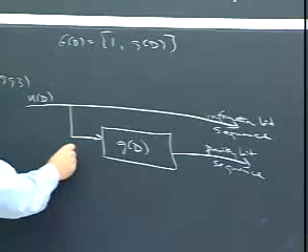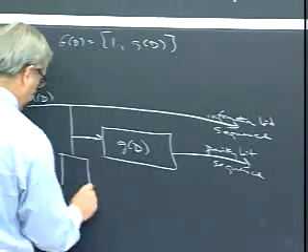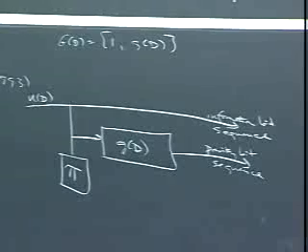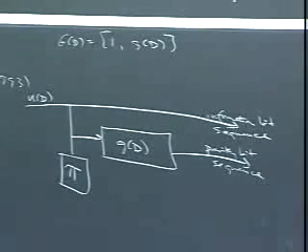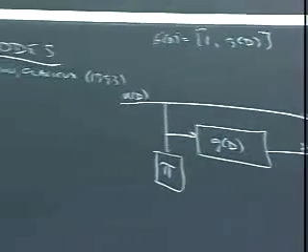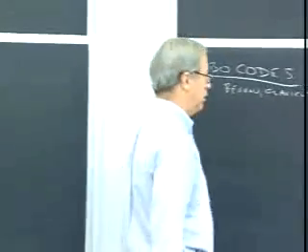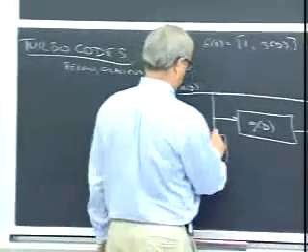Now, let me take the same information bit sequence and put it through a large permutation, which again I'll represent by pi. I want you to think of this as taking a 1,000-bit block and mixing it all up or something like that. Or actually it's better to use a so-called convolutional permutation, which is kind of stream-based, continuous, the same way that convolutional codes are.